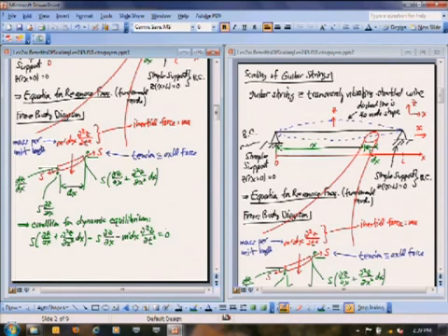If you solve this, you can come up with a frequency equation associated to this where you could solve that to finally get an equation for the resonance frequency, which looks like this for this particular problem. So that's f_i is equal to i divided by 2L, where L again is the length of this beam, as you can see from this axis on the right side there. And then this times the square root of S, that tension force, divided by the mass per unit length. Okay, so that then becomes the frequency equation.